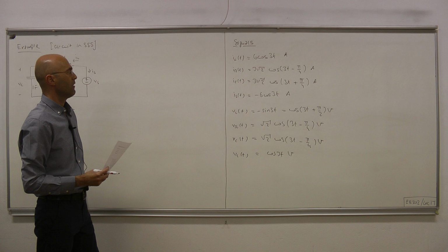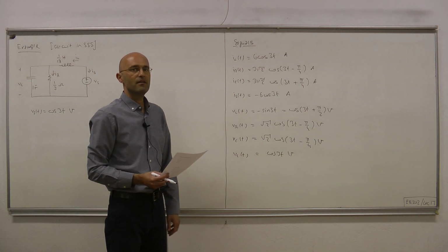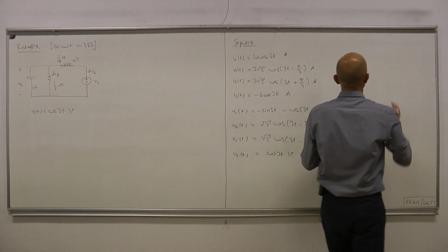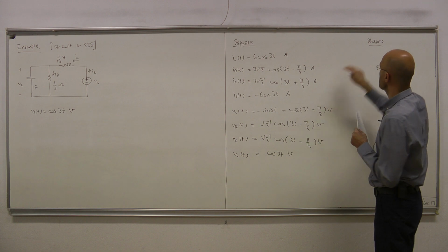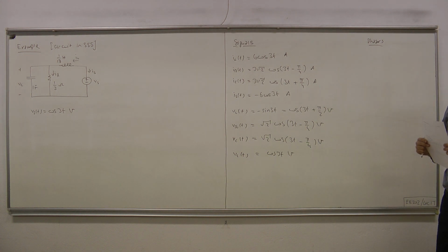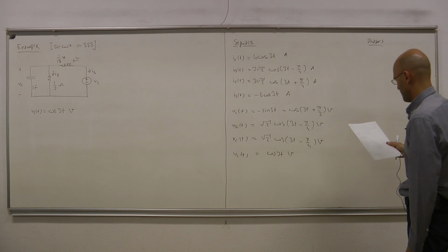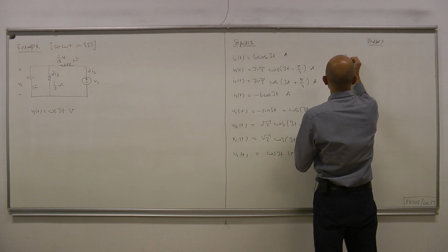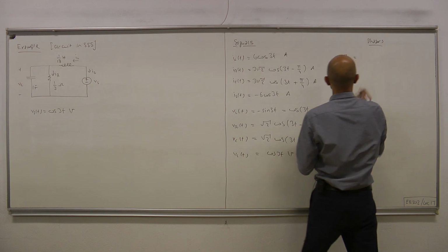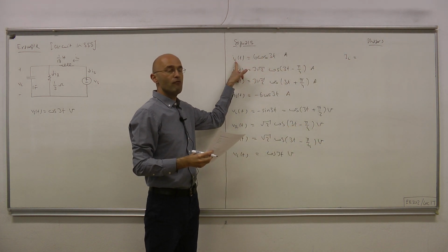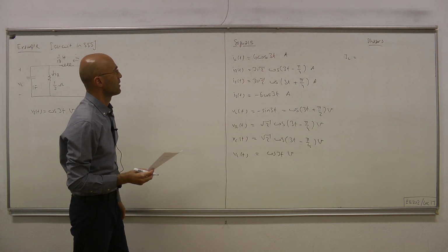Now, for those signals, let's quickly obtain their phasor representations. These are functions, but now we can express them as constant complex numbers. So we have IL. Note that by convention we capitalize the time domain letter.